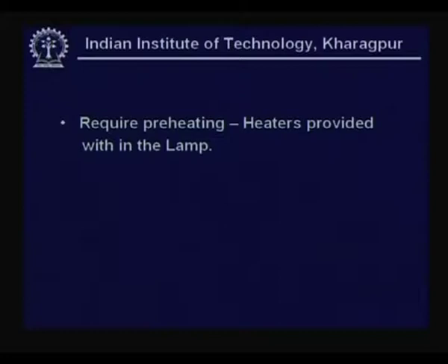Number two, there could be large potential drops at the electrode tips, that is cathode or anode, and this could be counterproductive in terms of the life of the discharge tube. Therefore thermionic emission is more or less the order, and therefore heaters are required to preheat the filament and these heaters are part of the lamp.